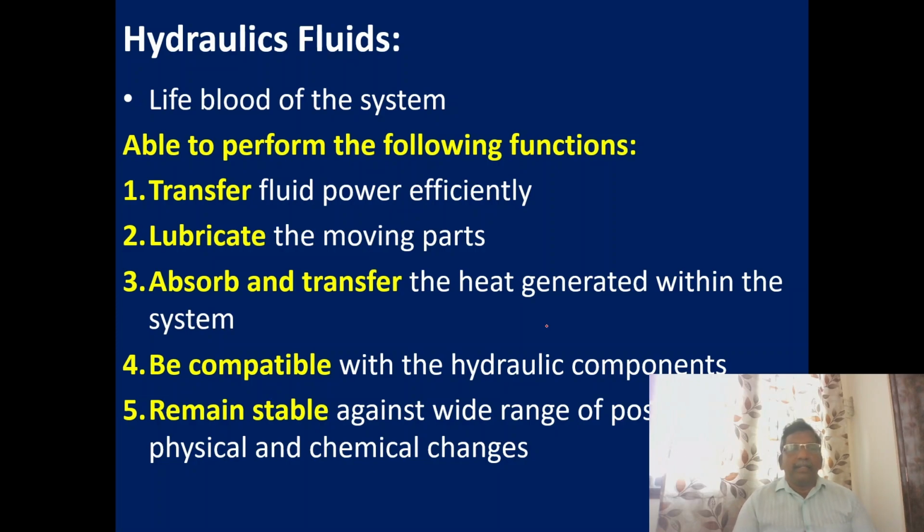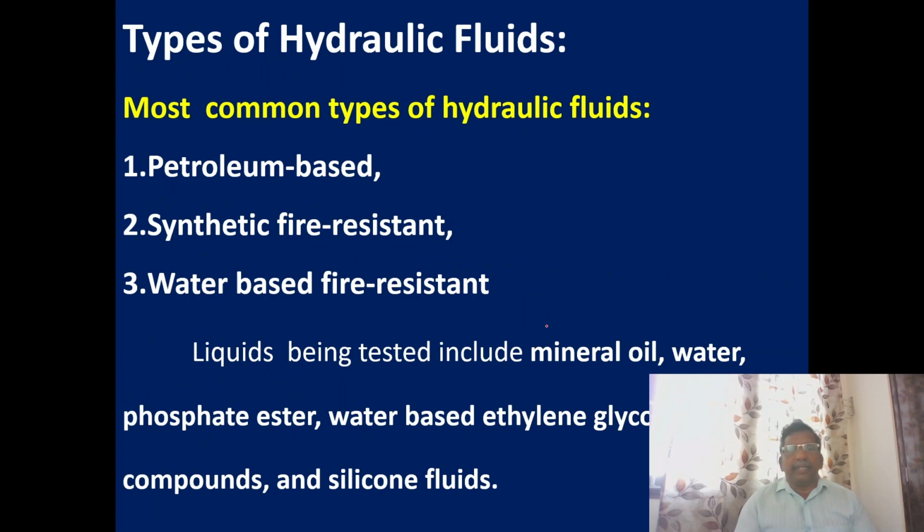It should be mechanically compatible with the hydraulic components, and remain stable against a wide range of possible physical and chemical changes. So these are the functions we need while we choose the hydraulic fluid. To summarize: transfer fluid power efficiently, lubricate the moving parts, absorb and transfer the heat generated within the system, be compatible with hydraulic components, and remain stable against physical and chemical changes.